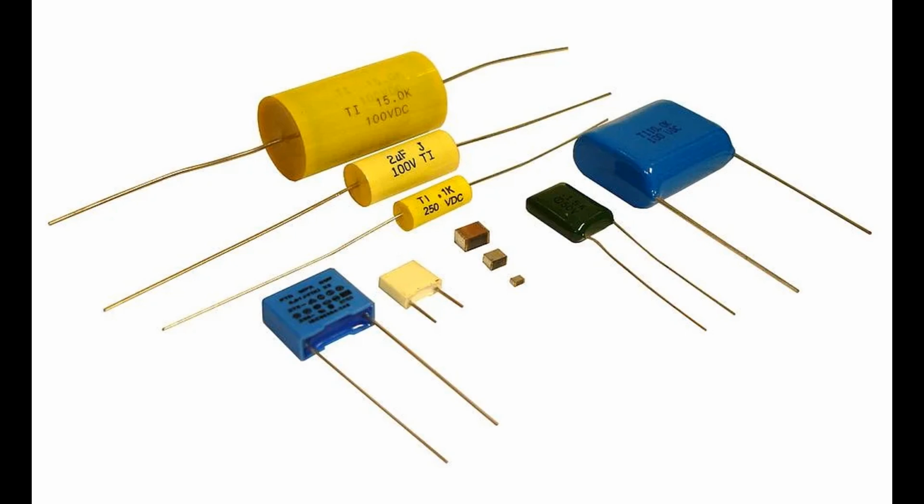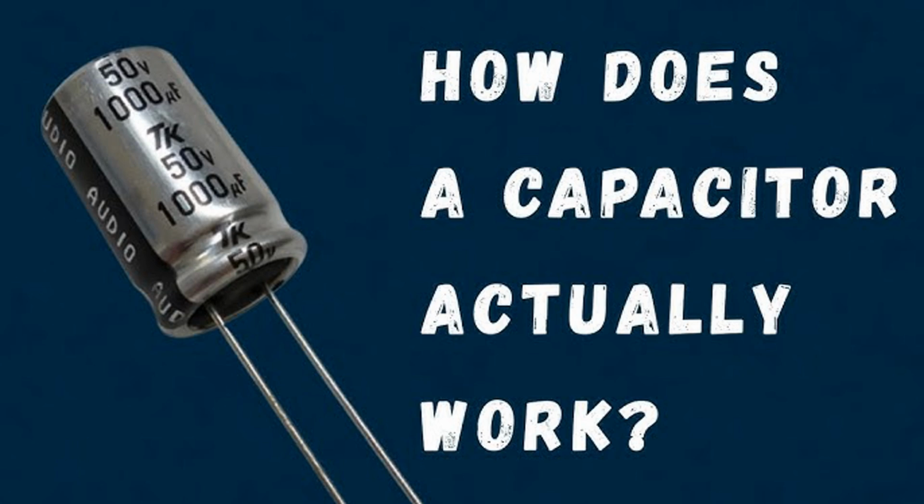Temperature sensitivity in some film types, like polyester or polystyrene. Non-polarized design may not be ideal for certain DC applications. Poor performance at low temperatures for certain film materials. Not suitable for very high capacitance, where other capacitors, e.g., electrolytic, are preferred.